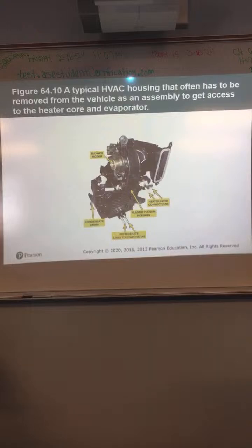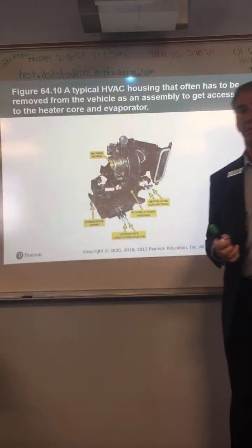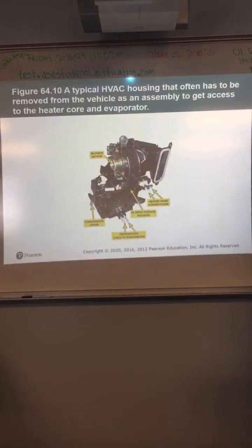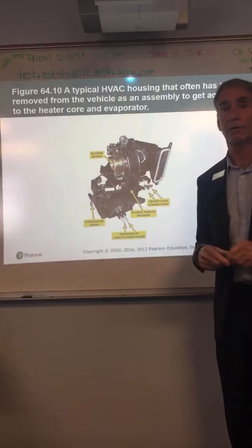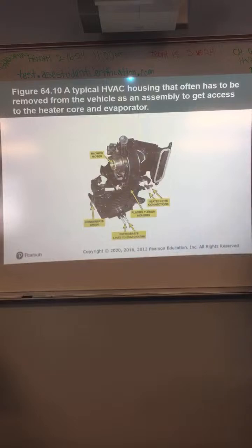Typically, you would have to remove that whole HVAC housing in order to service the evaporator core or the heater core. Blower motor, not necessarily. Since a blower motor could be considered a periodic replacement item, they don't want you to have to tear the whole car apart to replace it. So normally the blower motor is pretty easy to change. You can usually do a blower motor in under 30 minutes. They make it accessible.